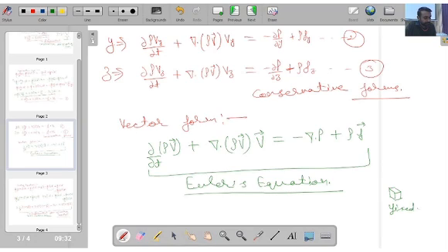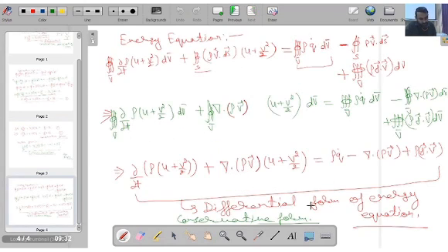It is not moving, but across this control volume fluid is flowing, and that fluid can have variations due to two factors: one is variation due to time, and another is variation due to spatial parameters in the flow field. That is something which I have done over here. So this is the differential form of the energy equation, and it is also called the conservative form.